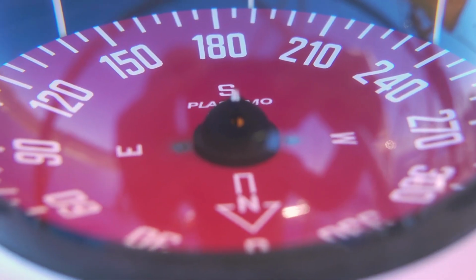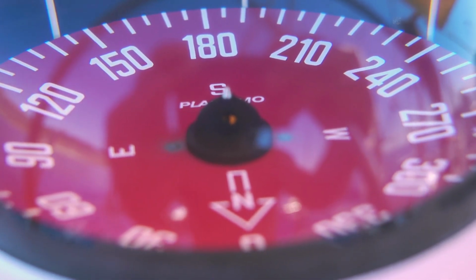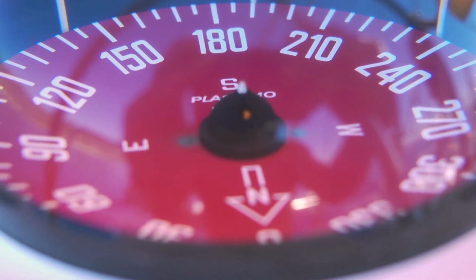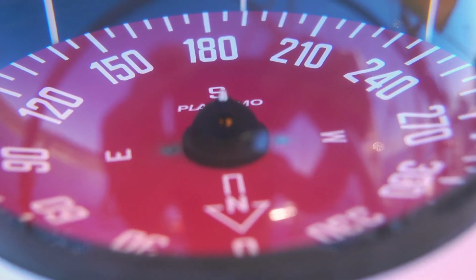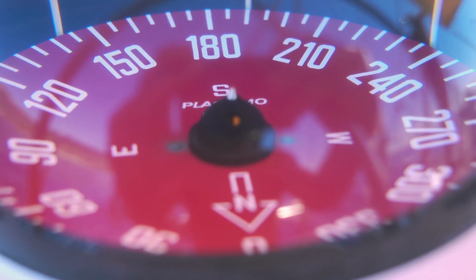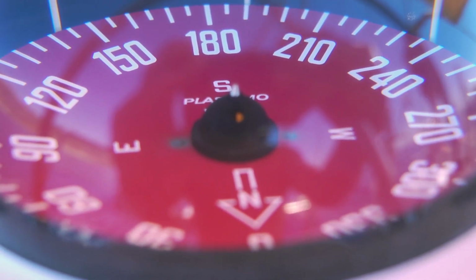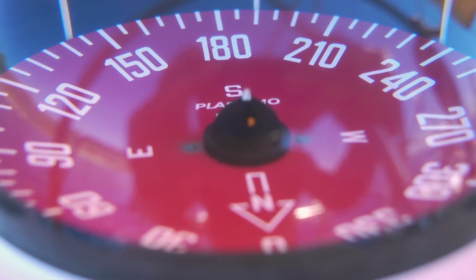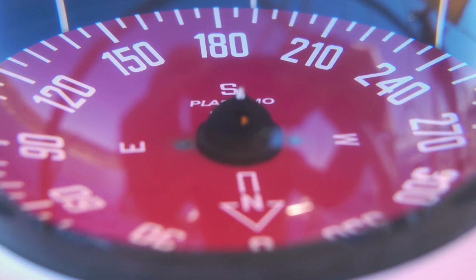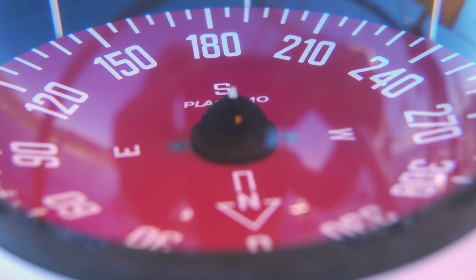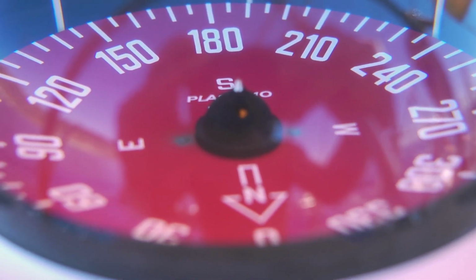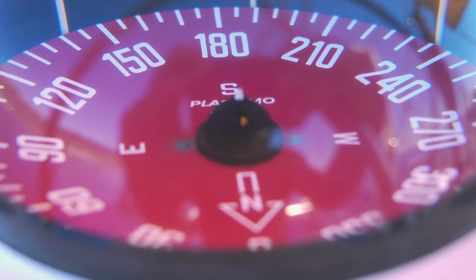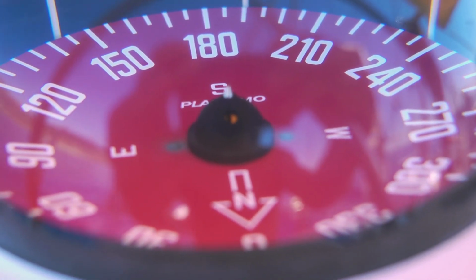It is pretty difficult to take a bearing with a steering compass, so a hand-bearing compass or compass binoculars are better, however, because these two compasses are mobile, it is difficult to know their accuracy in regards to deviation. It is best to use these compasses in an area of the boat that is least likely to be affected by any deviation, and for practical purposes, it is best to assume that there is no deviation, but just be aware that there probably is some deviation present, so these bearings should be used with caution.